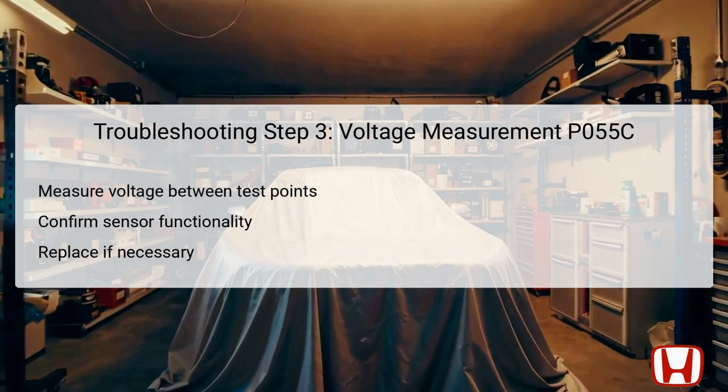If this voltage is confirmed, it indicates that the circuit leading to the sensor is operational. In this case, it would warrant replacing the rocker arm oil pressure sensor as it has failed to provide correct data to the PCM. A failure at this critical juncture can decisively impact engine function, thus requiring immediate action.